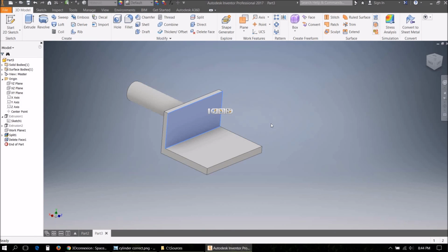The only thing you have to keep in mind is that you should avoid using metal materials in Inventor, because for many of the metal materials provided, either an Autodesk material or an Inventor metal material, it's very difficult to extract the metal color from it in 3D Studio Max. When an ID map is generated, it really can't differentiate between different metals. You might have one metal which is gold and another one aluminium, but if you convert it to an FBX file, they both look the same color, and if an ID map is generated, it's the same.